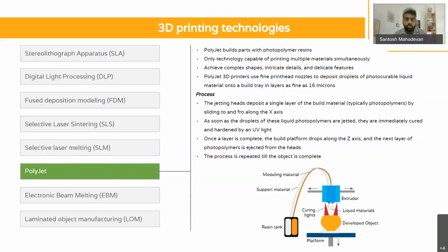And now the difference between this method as compared to, let us say, FDM and SLA or DLP, is that the parts come out perfect. I mean, almost one-to-one geometry wise. In the case of fused deposition modeling, although the method is very simple, you may notice that there are a lot of steps or a lot of layers that become too significant for the naked eye.